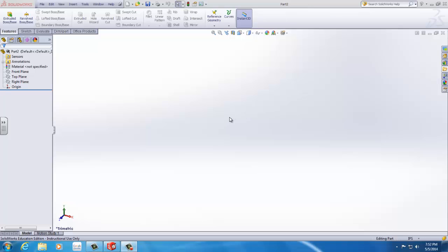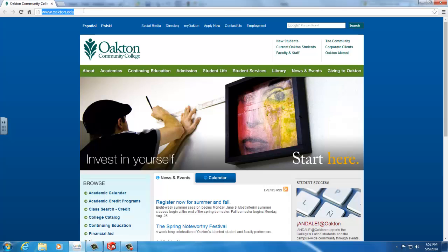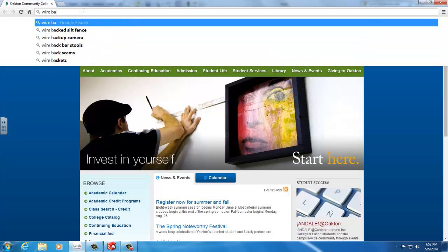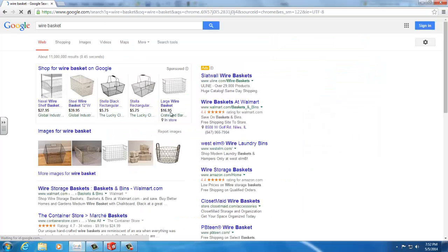Quick recap, so what we're going to do now is trace it over using SolidWorks. We start drawing, we start a sketch. It doesn't matter which plane you start with, but I recommend using the front plane, since we're going to use the front of, or actually it's really the right side of the canoe. We're using this image, and we should have it open. Okay, so that's what we're looking for.